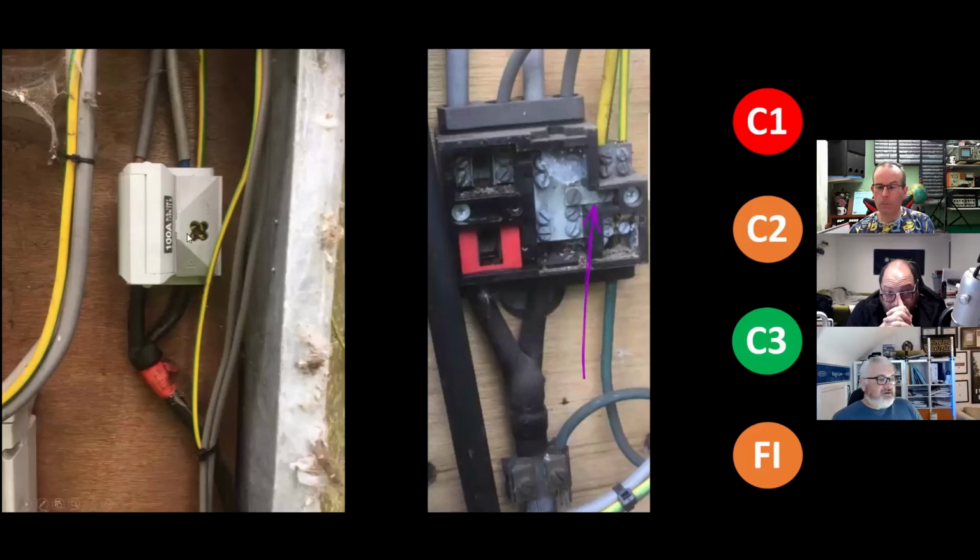Well, actually, no, do you know what? We can look at both, actually. Obviously, a really dodgy supply where someone has drilled holes to access the screw terminals. So that evidently isn't an authorized DNO cutout. But more importantly, the one on the right, that's inside one of those black cutouts with a PME link. So that's actually the link that you can connect or disconnect to make it either a TNS or a PME. So it's one of them rare insights that you can see.